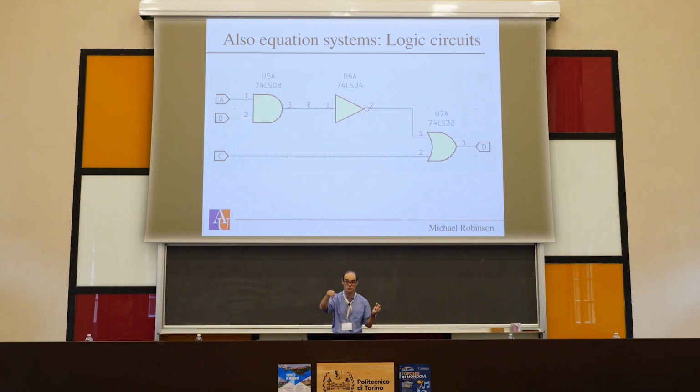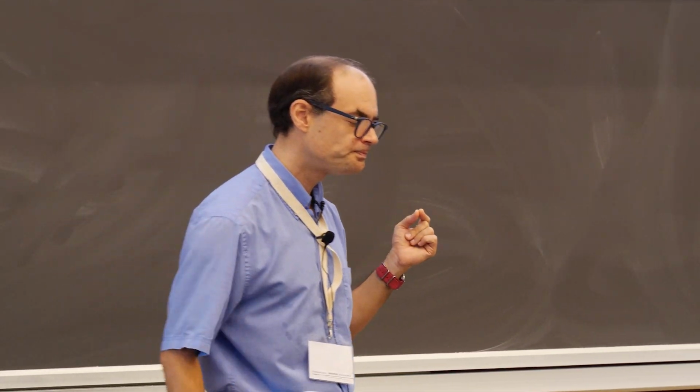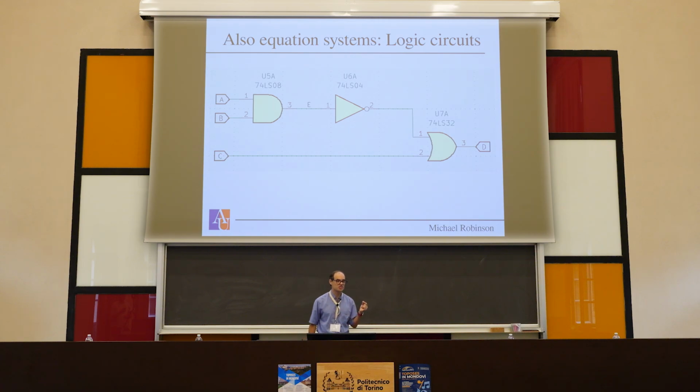Electrons are doing something on those wires. So really the ones and zeros correspond to either a voltage state or a current state, depending on the technology used to build these gates. These guys here, they are low-power Schottky circuits, so they are actually current signaled. So actually the presence of a logic 1 means current is flowing through the wire, and a logic 0 indicates that it is not.